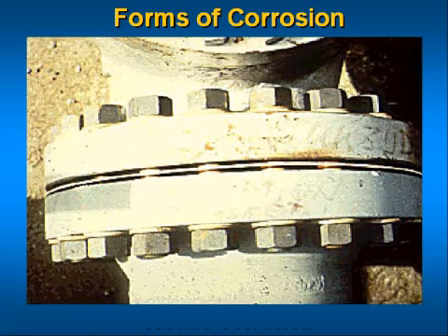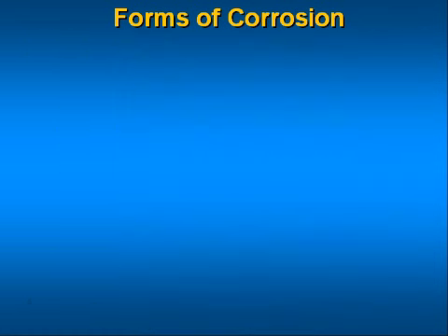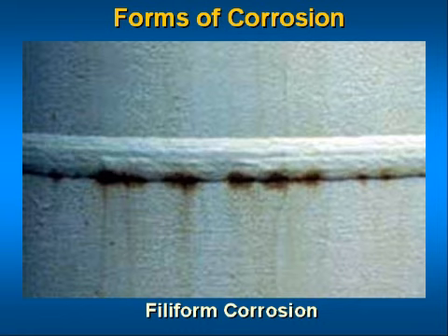Crevice or contact corrosion is the corrosion produced at the region of contact of metals with metals or metals with nonmetals. It may occur at washers, under barnacles, at sand grains, under applied protective films, and at pockets formed by threaded joints. Filiform corrosion. This type of corrosion occurs on painted or plated surfaces when moisture permeates the coating. Long branching filaments of corrosion extend out from the original corrosion pit and cause degradation of the protective coating. This picture shows filiform corrosion causing bleed-through on a welded tank.